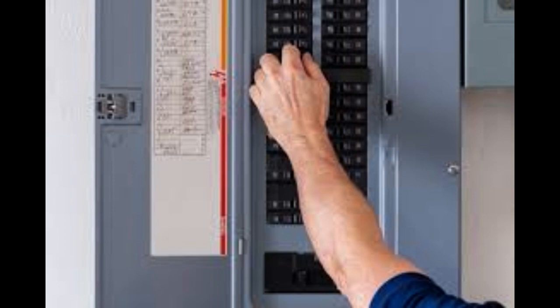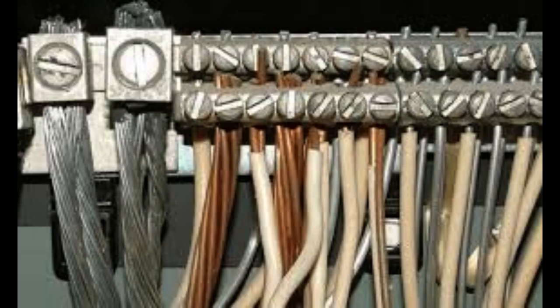F. Electrical cabinets and panel boards that are not accessible or do not have a minimum of 36 inches of clearance in front of them. G. Deficiencies in: i. Electrical cabinets, gutters, cutout boxes, and panel boards; 2. The insulation of the service entrance conductors, drip loop, separation of conductors at weatherheads, and clearances; 3. The compatibility of overcurrent devices and conductors; 4. The overcurrent device and circuit for labeled and listed 250-volt appliances;